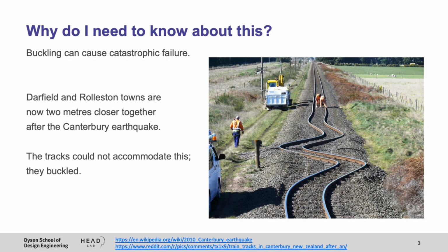So why do I need to know about this? Buckling can cause catastrophic failure. You may know that for structures, we need to remedy for internal forces that are caused by thermal expansion. For instance, we use supports that are called a roller support, which allows for expansion.